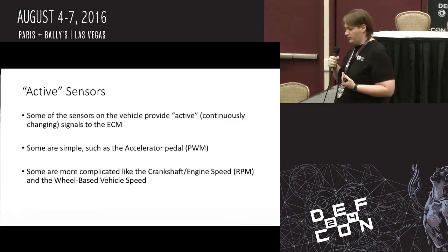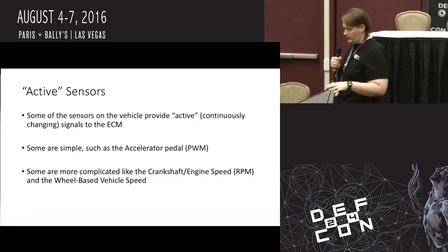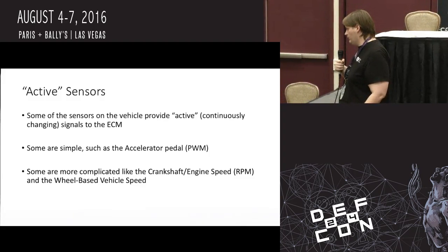One of them was the accelerator pedal. With no accelerator pedal, it wouldn't do anything. Even though a resting truck is just sitting there, the accelerator pedal is sending a position as long as the power of the truck is on. So that was a PWM signal. We hooked up a microcontroller and solved that one in a couple hours.